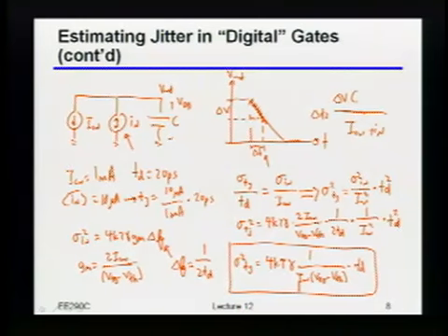Okay? And again, notice that the variance increases with the nominal value and not with the nominal value squared. Okay, so in other words, making the delays longer certainly makes the jitter worse, but relatively speaking, it's actually getting better. Okay? Does this make sense to everybody, or?